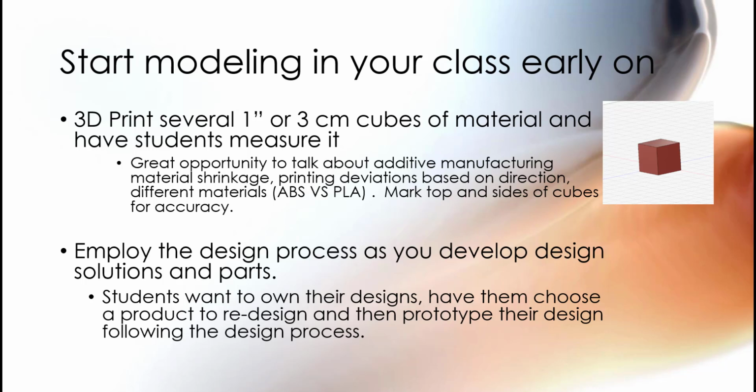Another option that you can do is use that 1 inch cube environment and print them around your different areas on your plate, on your additive manufacturing 3D printer plate, because then you can see which one is the most accurate area that it's 3D printing from.